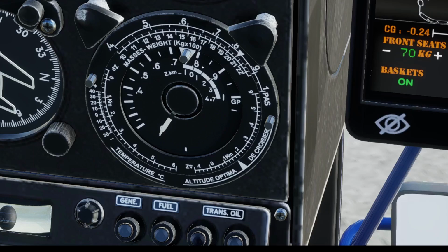But now you take 8, you take 9, the corresponding value here is going to be around 8.8. So here is 8, here is 9, 8.8 is going to be roughly here. So you will be able to load the helicopter up to 2,200 kilograms, it's still in kilograms, and still be able to perform an out of ground effect hovering.